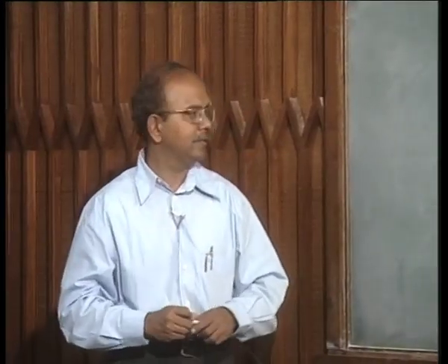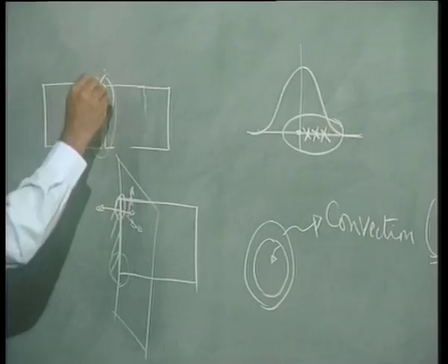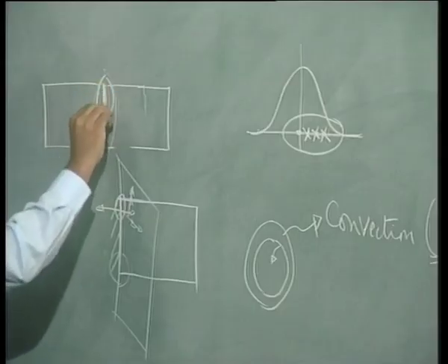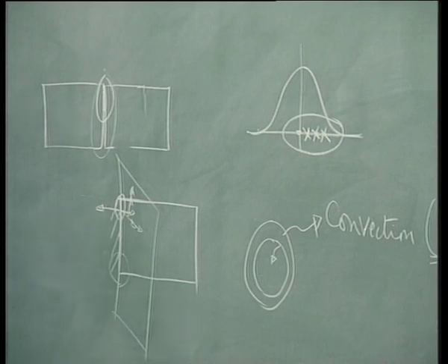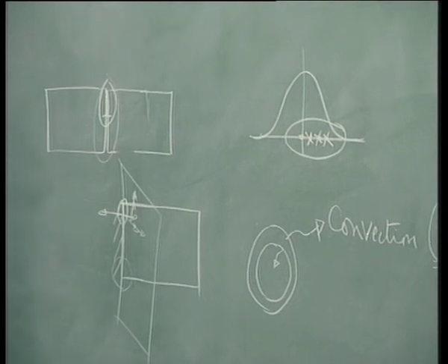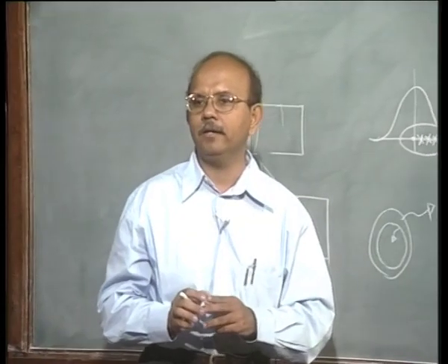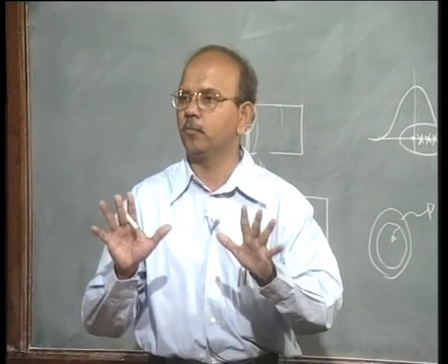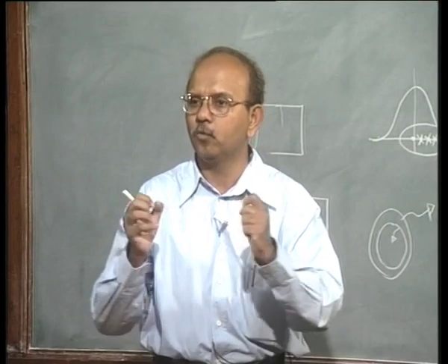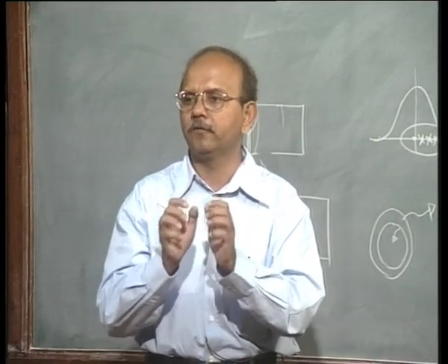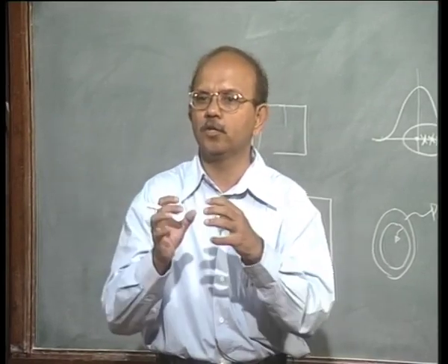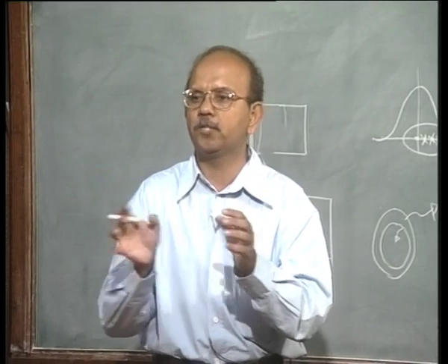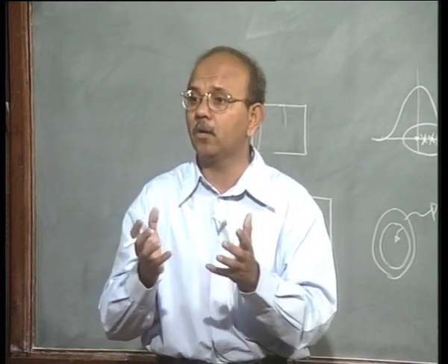For example, suppose I go to this point, I say I have welded up to this, anyway it is a 3-dimensional welding, does not matter. Suppose I just welded up to this, then up to that point, okay, I can say that there is going to be a symmetric boundary condition. There is no gap, both of them are welded, hopefully the fellow has done a good weld, so it is going to be one integrated piece, so no thermal expansions and all those things will be allowed.